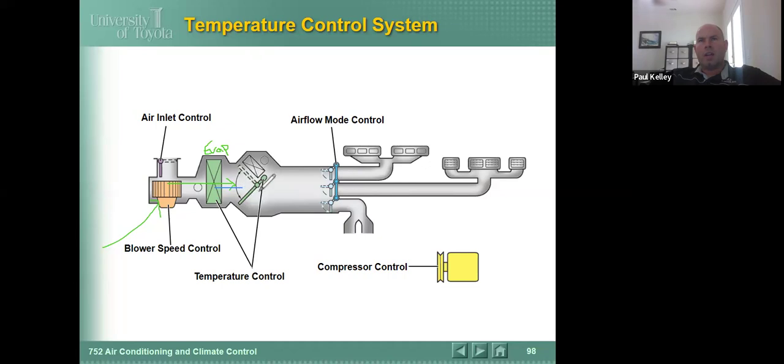And then cold air, depending on this position of this door, could go like this, and this would be cold air. And you get cold air and it feels so, so good. Am I right? But what happens if we move this door to the heat position, which would actually be where it's at right now? This is the heat position. It's blocked off this way. Which way does the air have to go? It has to go up like this through that thing.